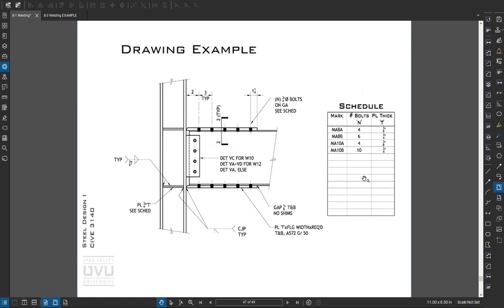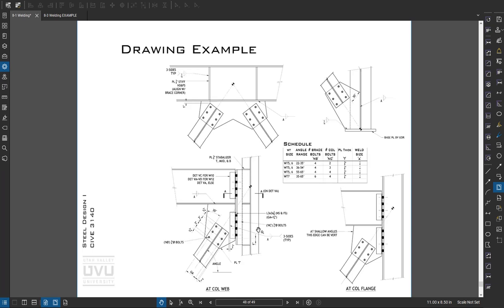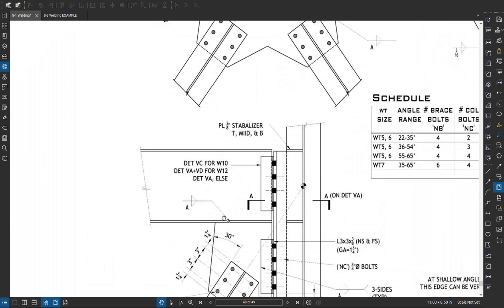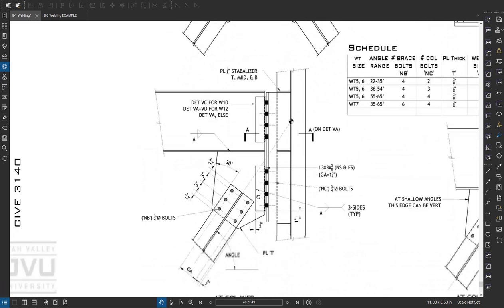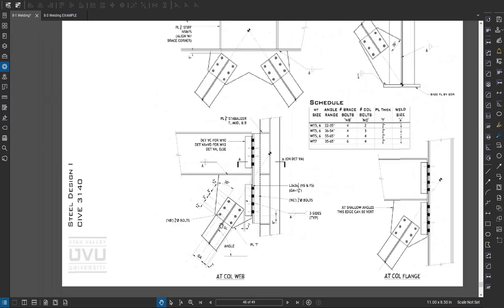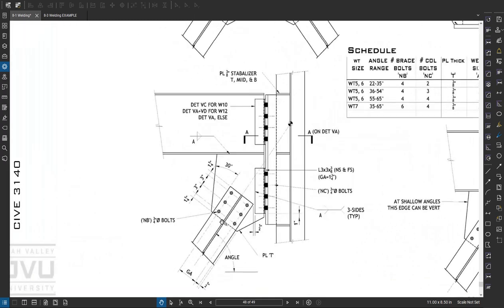Here's an example of a brace frame connection. So weld here between the gusset and the beam, weld here between the clip angle and the gusset. This brace could also be welded in place. Generally braces in the field, if we bolt them, it makes life easier, but doesn't mean you can't field weld braces in. It's done all the time.